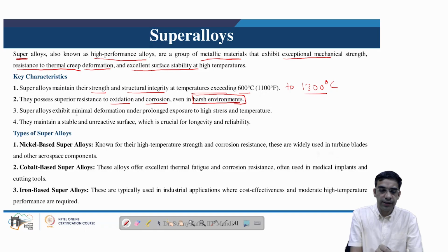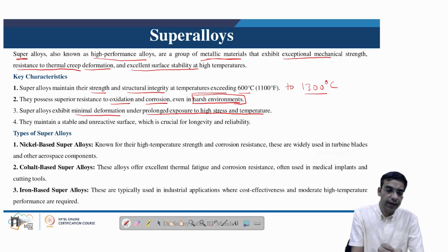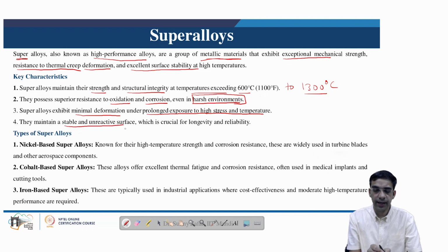Also, the superalloys exhibit minimal deformation under prolonged exposure to high stress and temperature. So this means the strain which is induced is minimal in creep sort of conditions, and because of all these characteristics, the superalloys are able to maintain a stable and unreactive surface, which is crucial for longevity and reliability of the gas turbine.